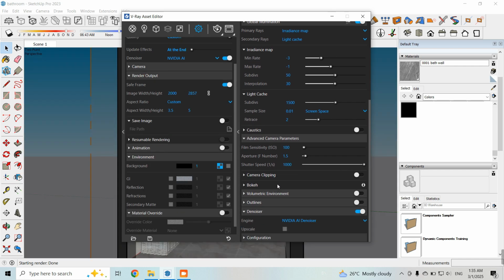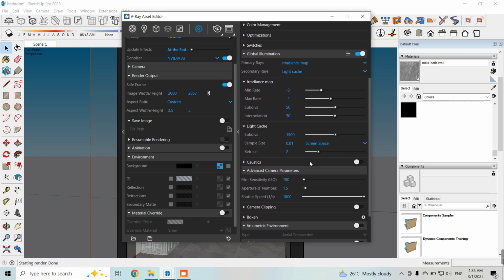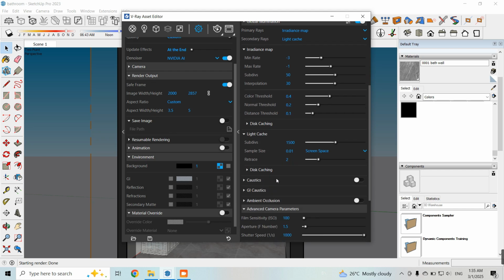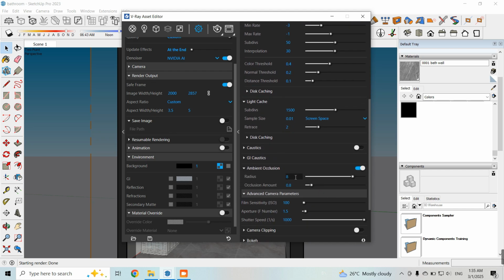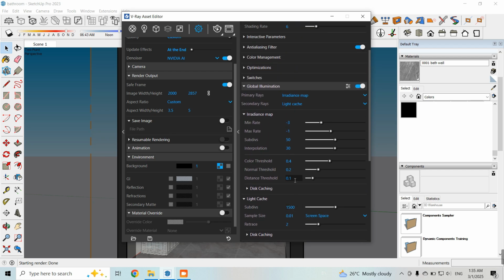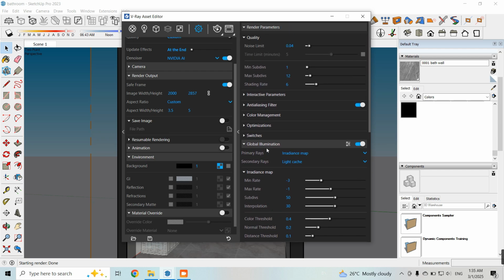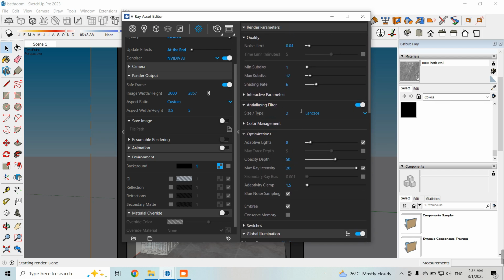So that's what you need. Anyway, there's ambient occlusion options 8 to 16. You can increase this to 16, but I will let it default here. Optimization, and I will change it to area.